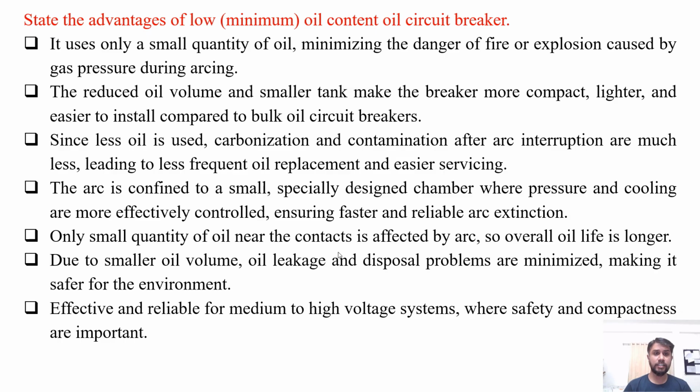State the advantages of low oil content circuit breaker. It uses only a small quantity of oil, minimizing the danger of fire or explosion caused by the gas pressure during the arcing period. The reduced oil volume and smaller tank make the breaker more compact, lighter and easier to install compared to bulk oil circuit breakers. Since less oil is used, carbonization and contamination after the arc interruption are much less, leading to less frequent oil replacement and easier servicing.